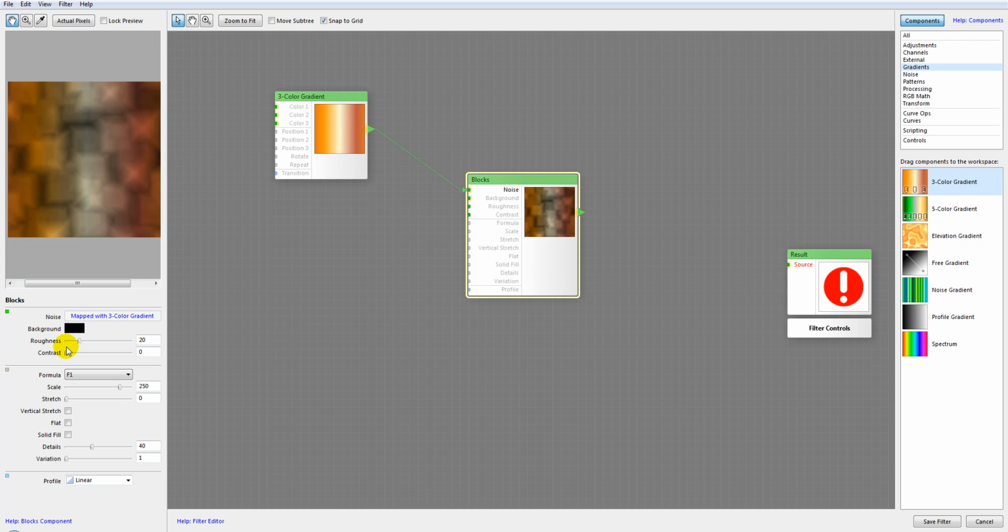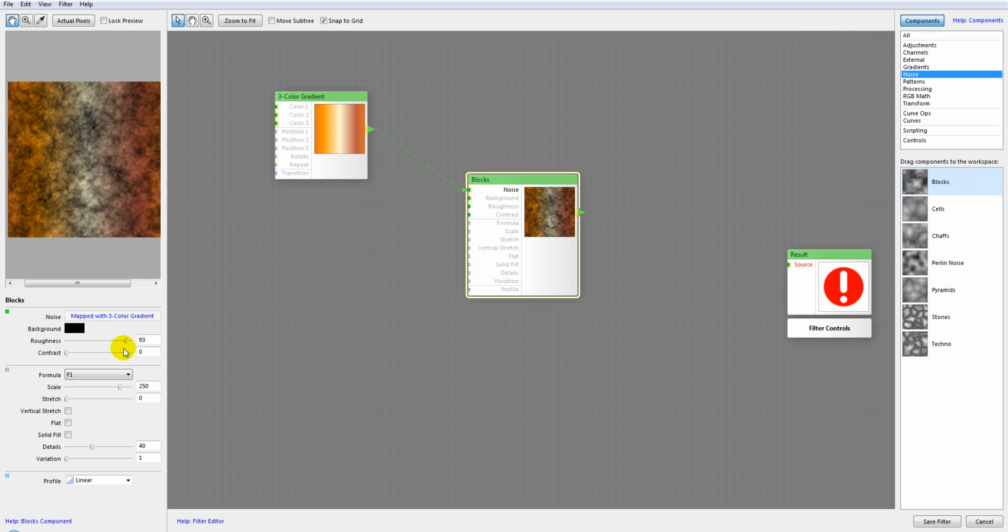Next option is roughness, and this is a map input as well. This will adjust the noise roughness. Technically, roughness defines the relative transparency of the octaves of the noise it's composed of. So right here you can see we have a little bit more detail in our algorithm. However, at some point we start losing the overall shapes of our blocks. So what did we have before?